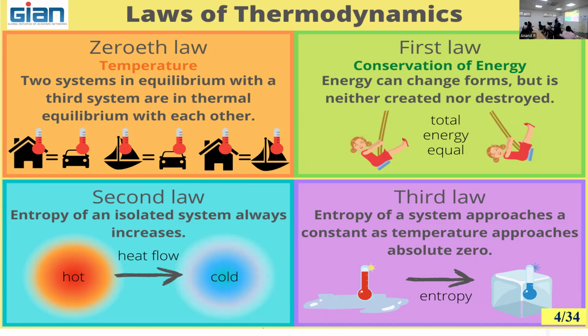So we want to find out the efficiency of the heat engine. The symbol for efficiency is eta, equal to how much work is coming out. Efficiency is always output by input. Here the output is energy in the form of work divided by energy in the form of heat. For a given amount of heat, how much work is coming out. This is also equal to the heat I am supplying minus the heat I am rejecting to the surrounding.